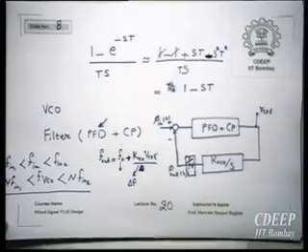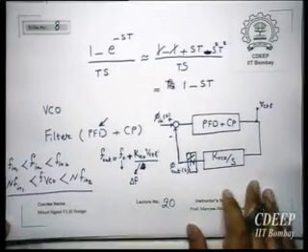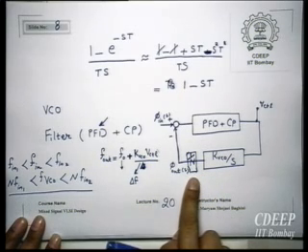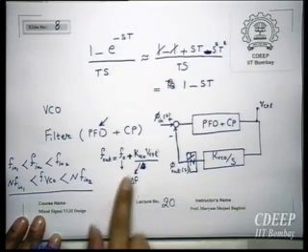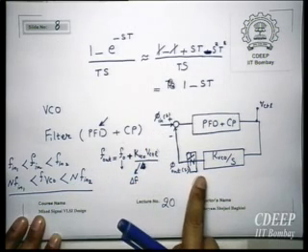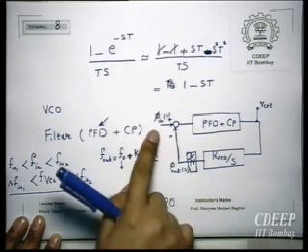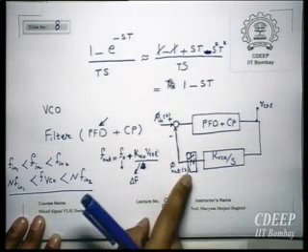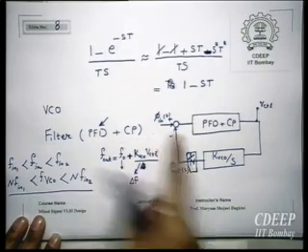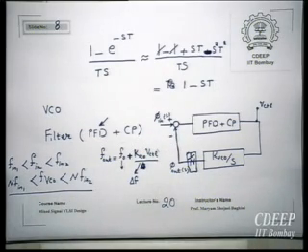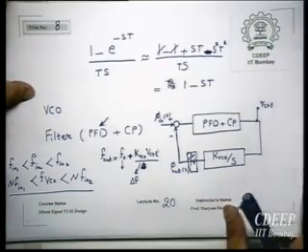So for example, if I want to design a PLL which uses divide by 16 and generates a 1 gigahertz to 2 gigahertz frequency range, then that means I will know what my input frequencies are. This is 1 upon 16, so this range will be 1 gigahertz to 2 gigahertz, and then the input frequency accordingly will be defined. So this is not a big deal. The main part is how to decide about the filter.